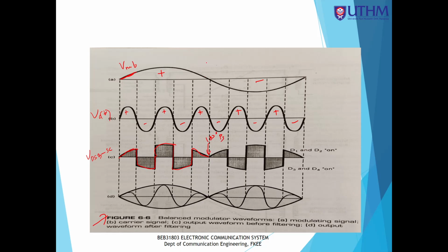Over here, the message signal goes through the zero crossing, that means the message signal changes polarity from positive to negative, so the output will have a 180 degree phase shift, so the wave will invert. You see that instead of going down, it will go up like this.